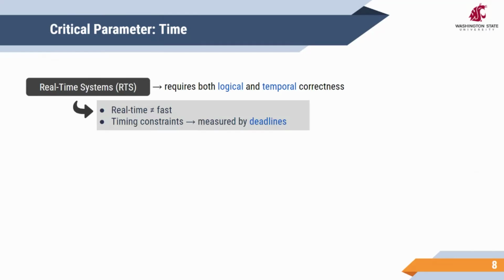But what we mean here in real-time cyber physical applications doesn't mean we need to perform fast computation. Instead, we need to perform the required functionalities of the applications or tasks within their predefined timing constraint. And often those timing constraints are called deadlines. So each real-time application in the system must meet its deadline to make sure the system remains operational.